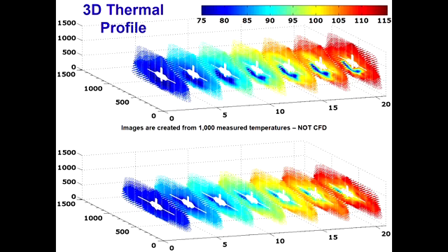So now we can monitor air binding not just from an outlet tube sheet perspective, but we can monitor air binding in the third dimension throughout the condenser. And this provided us for this project some very useful information to design a retrofit to get rid of this air binding. So again, this is the temperature profile for this particular Westinghouse.